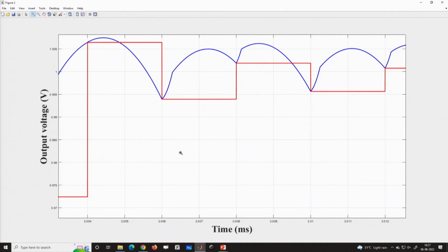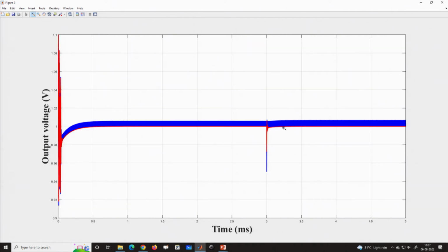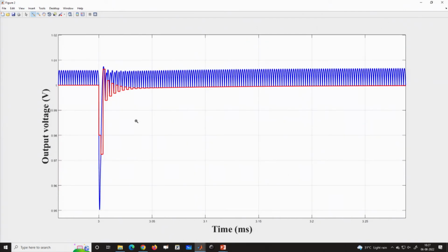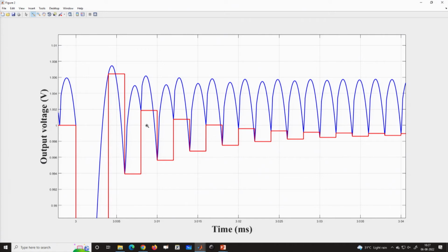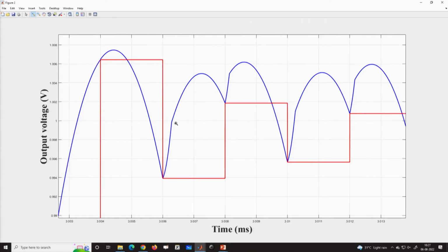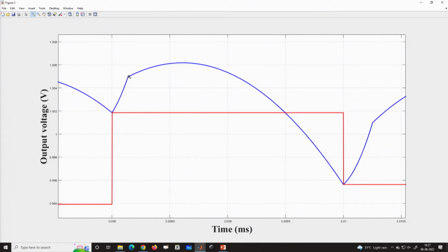So, there is no delay considered here, but there is a delay due to the modulator. If you talk about analog control, the switching is happening here. If you take one full cycle waveform, the switching is happening here, whereas the sample is picked up here. In analog control, until the switching happens, your output voltage will change and it will be reflected in the controller, so the controller output will also get updated until the point of switching.